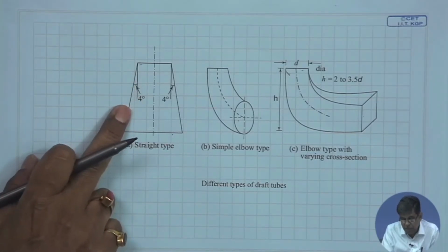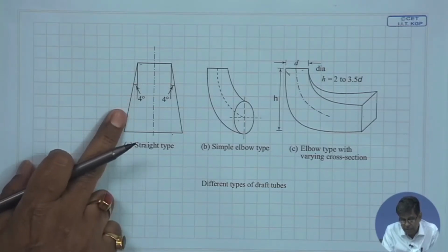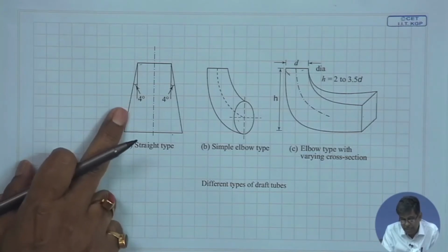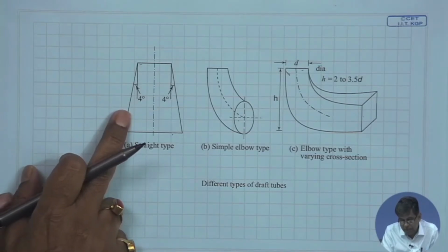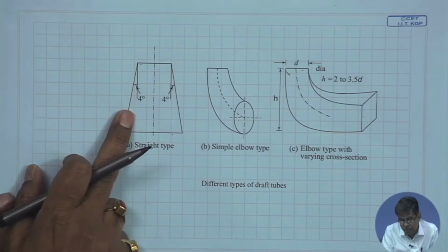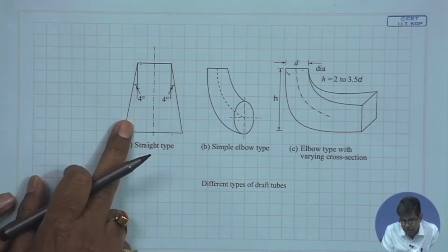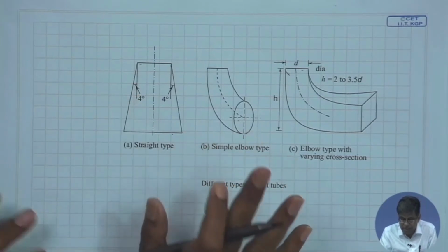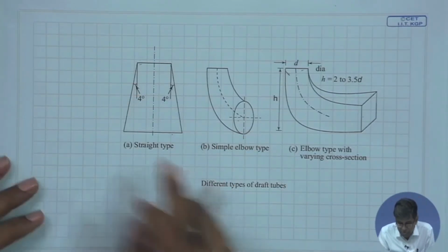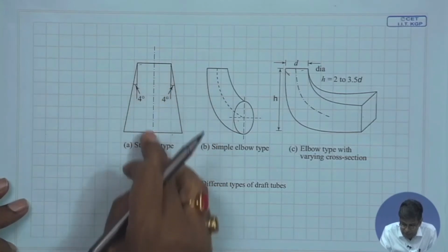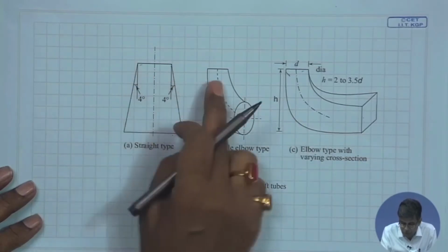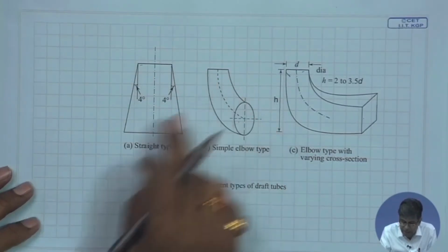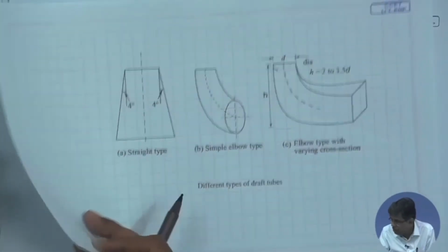The particles within the boundary layer have very low kinetic energy because of low velocity due to the interaction with the surface, that is the no slip condition. At the surface the velocity along the surface is 0 relative to the surface. So, low kinetic energy particles close to the surface cannot surmount this adverse pressure gradient and they flow in the opposite direction. That is precisely the boundary layer separation phenomenon. So, to avoid this, in case of any flow with adverse pressure gradient, in this type of flow in a divergent duct, in a diffuser, we have to always take a caution that the divergence angle should be kept below 8 degree to avoid this separation.